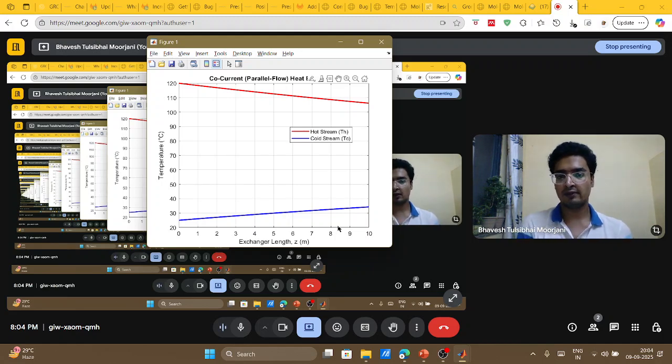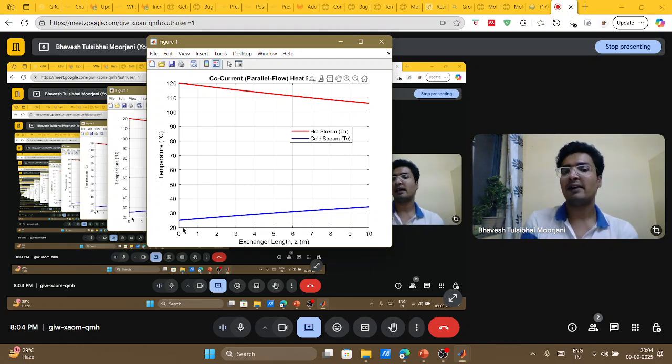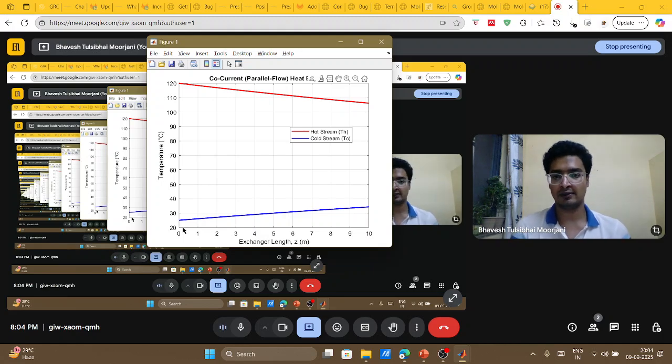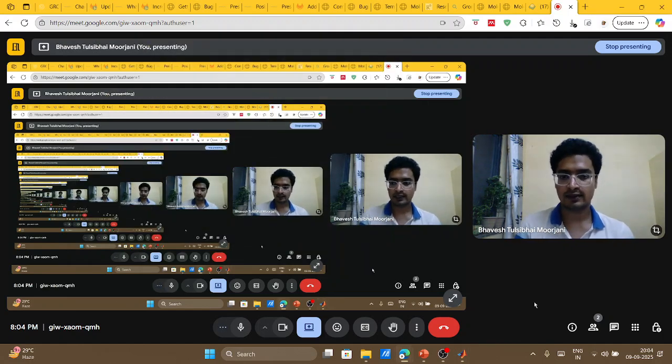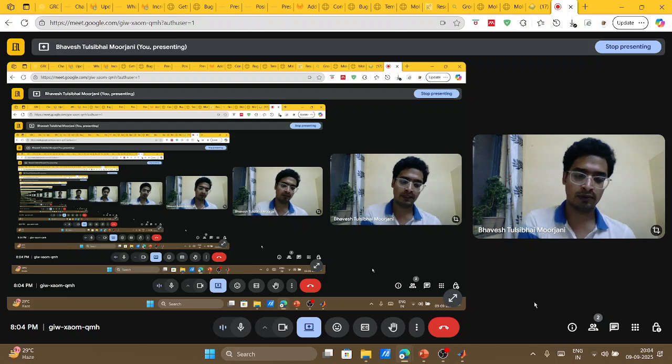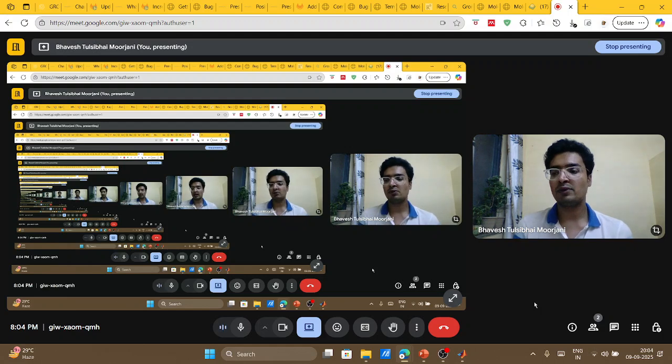But now, in order to solve this, the problem has become something else, because in ODE45 what I needed was the initial value at Z equal to 0, but now I don't know the values of TH and TC at Z equal to 0. I only know the TH value at Z equal to 0. The TC value is known at Z equal to L, right? So my question is, what kind of problem have we now created? It doesn't appear to be an initial value problem. I don't know the initial value of TC at Z equal to 0. So in that case, how do I solve it?